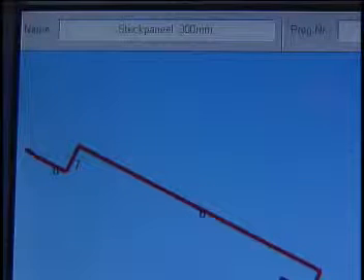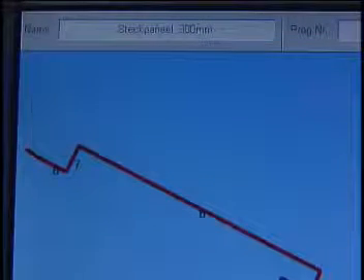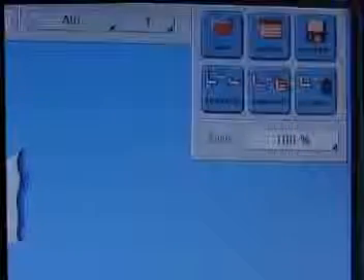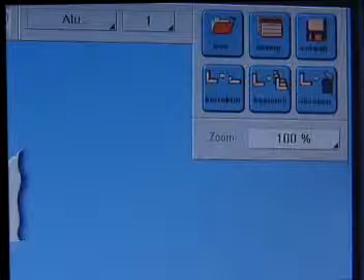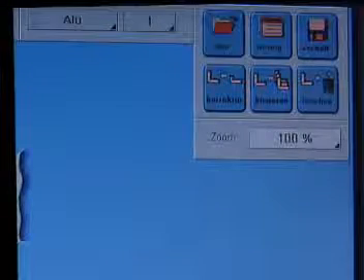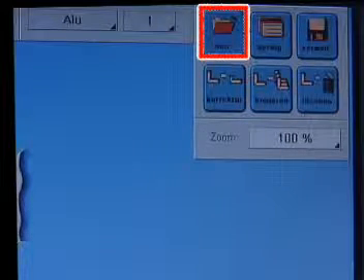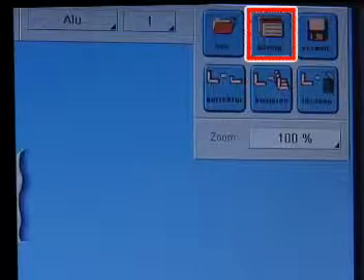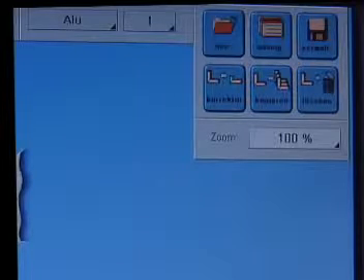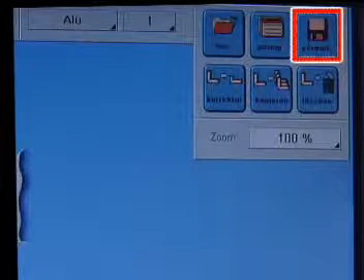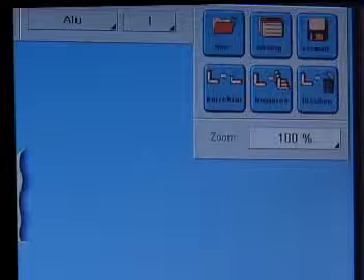The main screen has different groups of buttons. On the top end are the profile headers, with program name and number, cut size, a pull-down menu with a choice of the most common materials, and allocation of material thickness from 0.5 up to 6 mm. In the top right corner are the program administration functions for creating new profiles and for listing and searching profiles. The Admin button leads to all submenus for system administration.